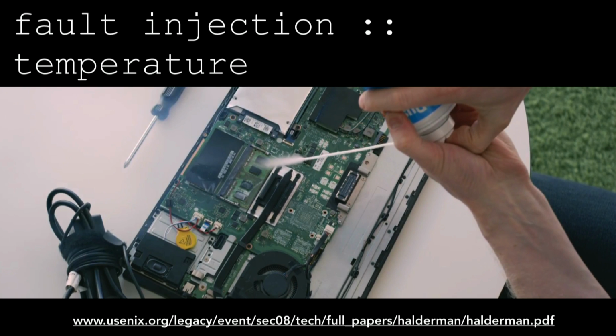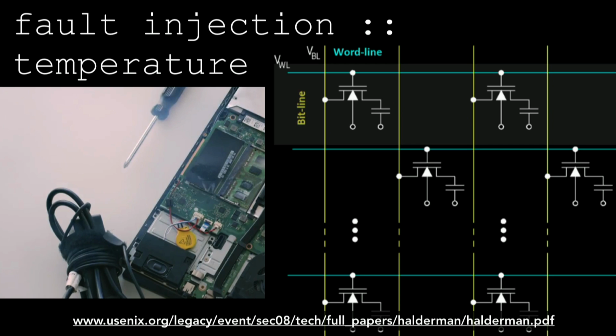The problem is, I could try to pull your memory out of your computer, but memory is volatile, right? It will disappear in a second after pulling it out. But if we're looking at DRAM, DRAM is really just a grid of transistors and capacitors. In a single transistor and capacitor, the capacitor is holding a bit of information. It's either a 1 or a 0, and that is constantly being refreshed. A capacitor is really just holding a voltage, a difference of electrons between the two poles.